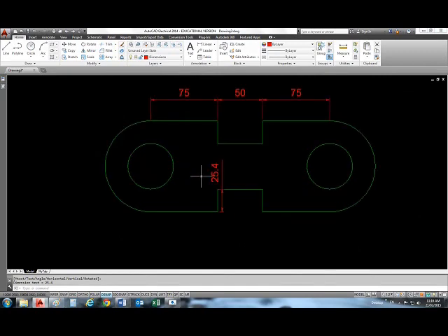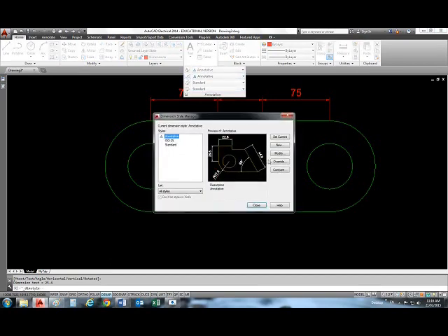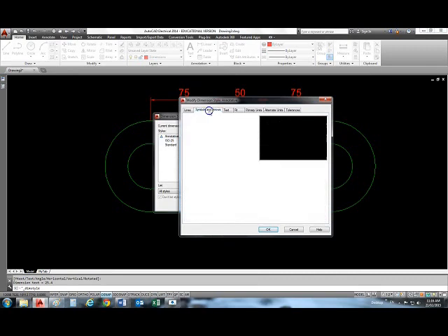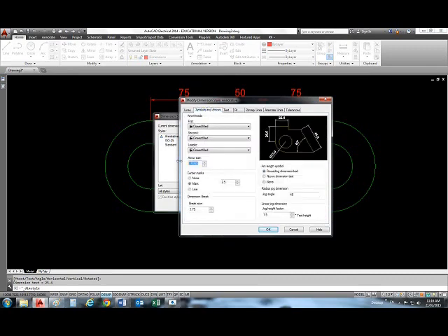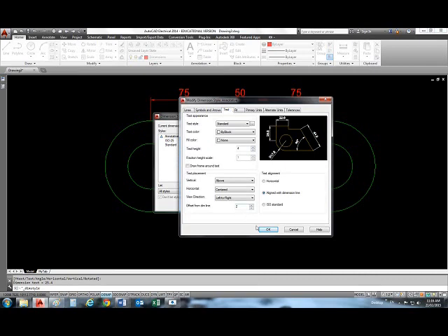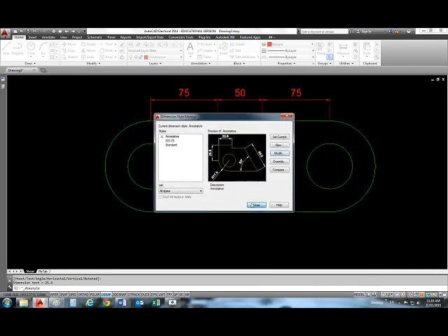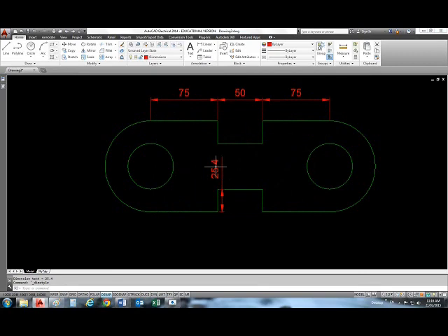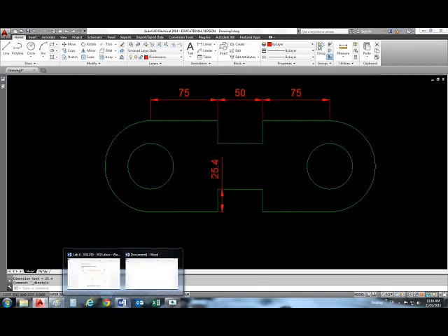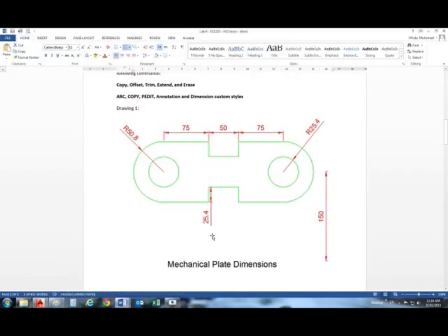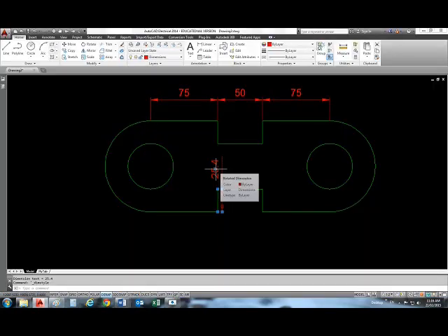Okay, if that doesn't look too good, the arrow sizes, the arrowheads seem to be smaller than they should be. So let's go back and double check the arrowhead size. I went back to 2. That's why it needs to be 4. Text needs to be 4 and 2. Close, and that's better. Now this one needs to be below. So let's go and click it.